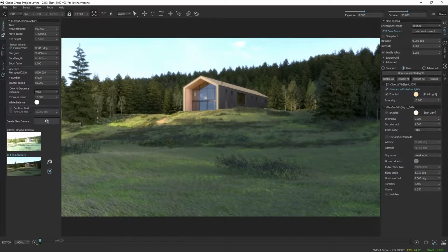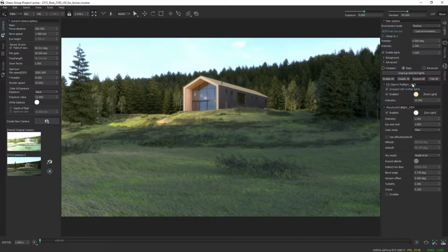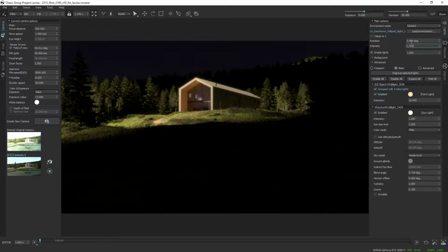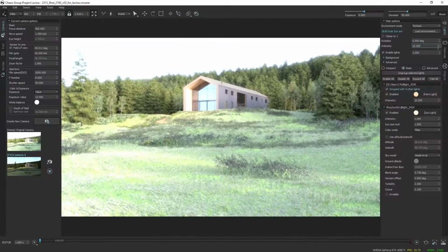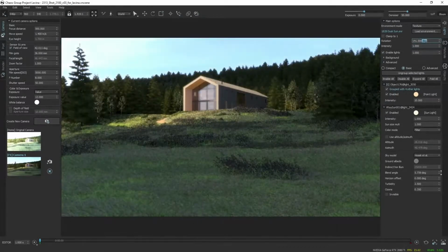We have the lights section, which allows, as you see, assigning different, for example, HDRIs. For example, I can use this one. These are the recent ones that I used. And this guy doesn't have too much intensity, so let's bump it up and see. Okay, this is more of a night sky. And quickly go back to the original one. And because currently this is using 10, let's bring it back to 1. Change the rotation of the HDRI and see it affect the image-based lighting in real time.